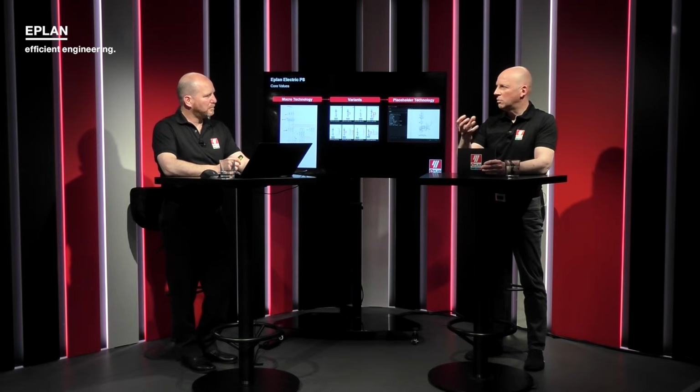And what we saw, by just changing these value sets, you can extremely fast react on changes that are coming maybe from the mechanical design. If they change the motor size, for you it's a click. And maybe you can cheat the guys a little bit in mechanical design: I have to change my schematics, but it's done by a click. And you don't have to remember it; it's stored inside of the library, right? Absolutely. And I think that especially the more experienced engineers and the more experienced users of ePlan can be the guys who in future create these libraries, and then new colleagues are able to onboard much faster into the system. Absolutely. Great. I think there's more.